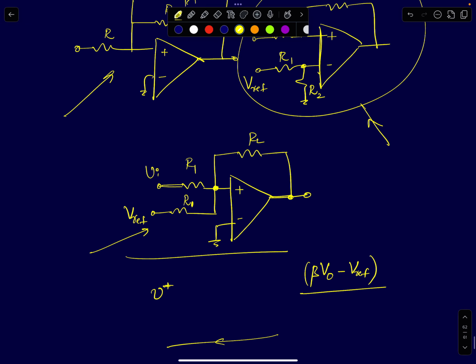If you connect the offset voltage at the non-inverting terminal, some additional reference voltage, the effect is similar. The final outcome is that you will be creating an asymmetric characteristic, but now instead of shifting it to the right, you will be shifting it to the left, because if your Vref is positive, you will shift it to the left. If your Vref is negative, you will shift it to the right.